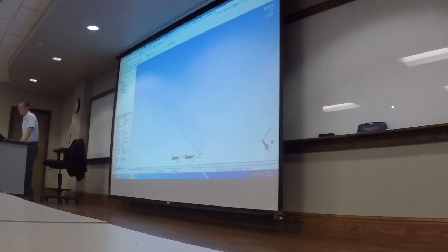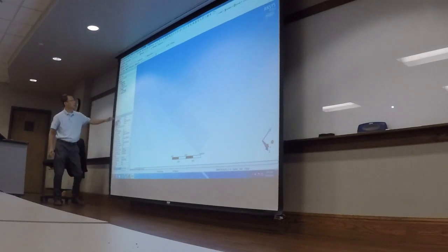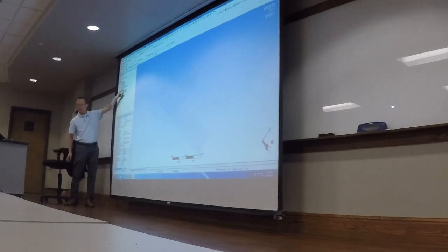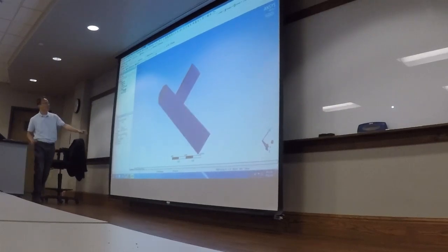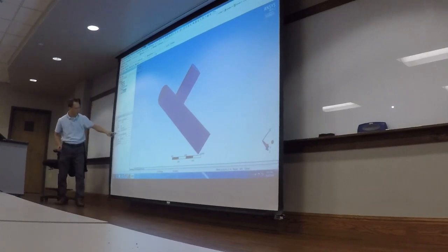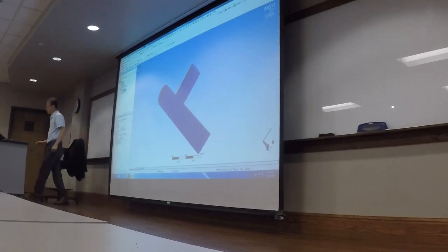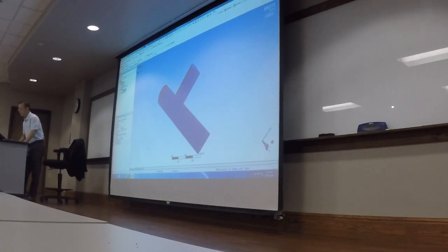Now, click on this body sizing. This is about mesh. Click on the body sizing. Now we're going to change this element size. If we still remember from the tutorial, that measuring number is 6e negative 3 meter. All right, I think that's all we want to do.